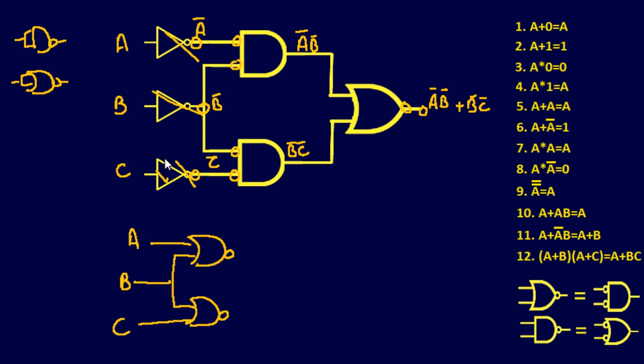So right now we knocked out that one, that one, that one, knocked out that one, and that one. And then what we have left is these two. So it's going to go to another NOR gate. For some reason I can never do these curves very well. And then we have one more dot we need to take care of. So what we're going to do is, I'm going to do that inverter. There we go. So right there, it looks like we have a complete circuit using only one chip of NOR gates. So that's not bad. So let's go ahead and check our answer.